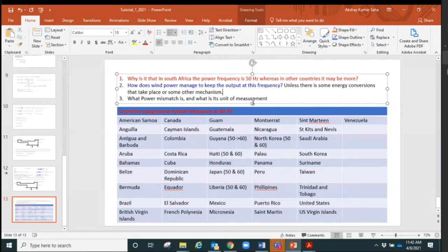If you connect more load, the inertia will respond immediately and drop its speed, giving energy from its own kinetic energy because of rotation. A similar thing happens if you withdraw some load, so the energy is not being consumed now, and that excess energy from the load side will be reflected on the generator rotor.